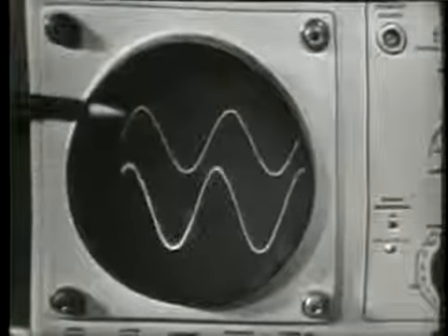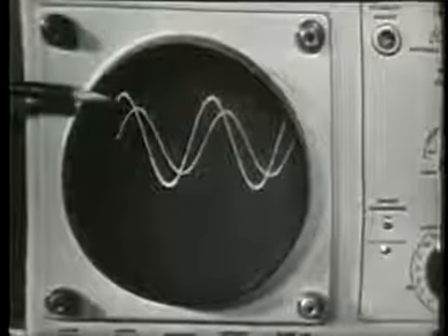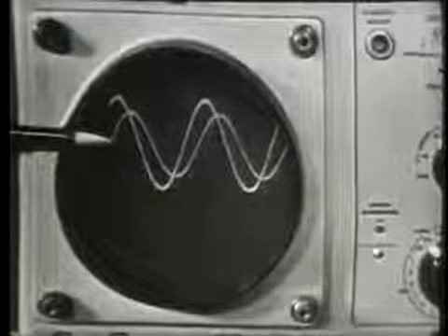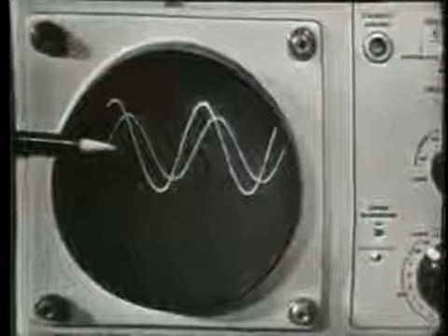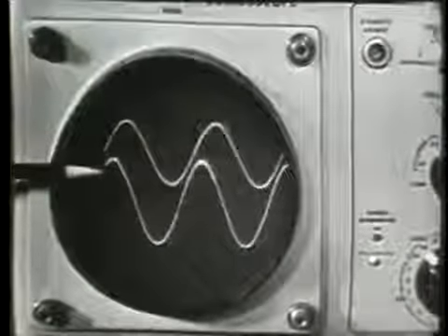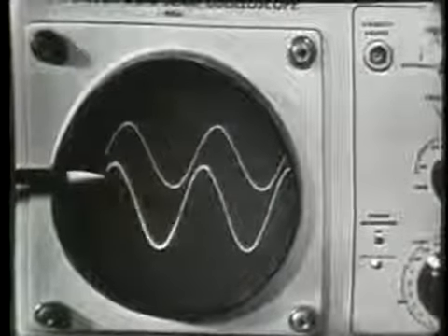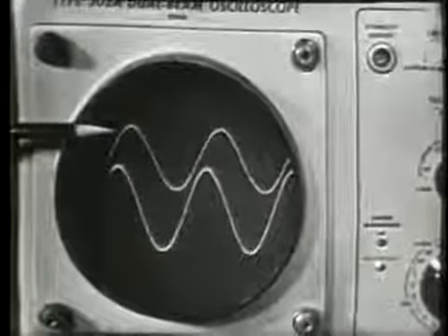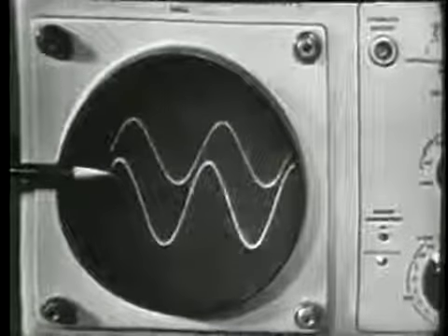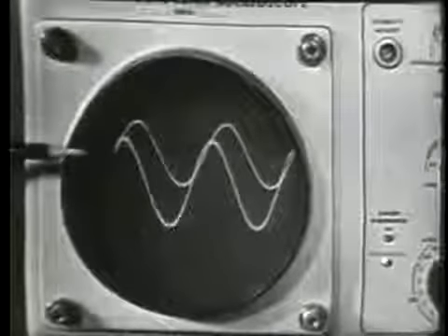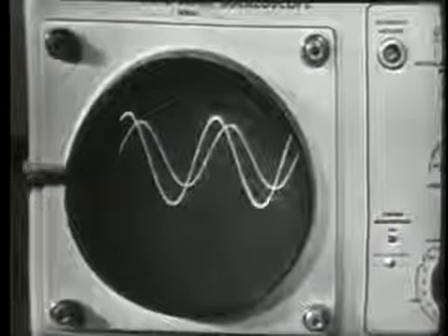First of all, we can check the relative amplitude by moving the lower waveform up. And of course, we can see that the voltage applied is greater in amplitude than the voltage across the resistor. You'll also notice there's a definite phase difference. If we move the waveform down just a little bit, you'll notice that the voltage applied is reaching a maximum positive value before the voltage across the resistor reaches its maximum value. Well, this indicates to us that the voltage applied is leading the voltage across the resistor by some degree. This, of course, you recall, is what we found when we plotted our vectors of these voltages.